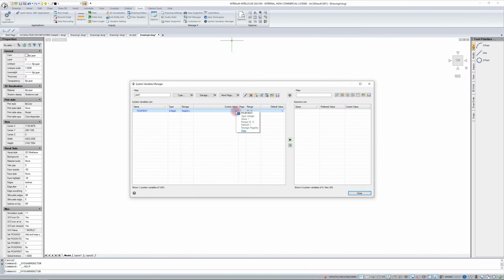But if we disable this variable, set it to 0, this is when we select lines, click delete, and the program needs confirmation from us that this element is indeed to be deleted. So we must then confirm via enter. Sometimes it happens that users ask what happened because they can't delete a line. By accident, this variable has been changed, and it is because of this that they cannot delete. You can then restore the default settings, but if we still have some other settings of our own, it might be better to go to this manager and modify it for ourselves, turning the appropriate setting back on.